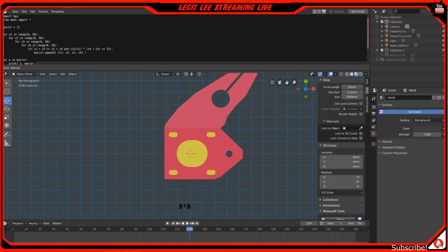And then my pivot point, we can go down to, I believe it was a 0.4 for the tooth profile. I'm going to do a 0.8 because I want to make sure it runs in smoothly and won't be rough or feel weird or anything. And I want to do a little wider. If I need to go bigger later, I'll do that, and that's fine. So on the website, all I have to do is input that information. And if you want to see it, I can show you guys really quick.